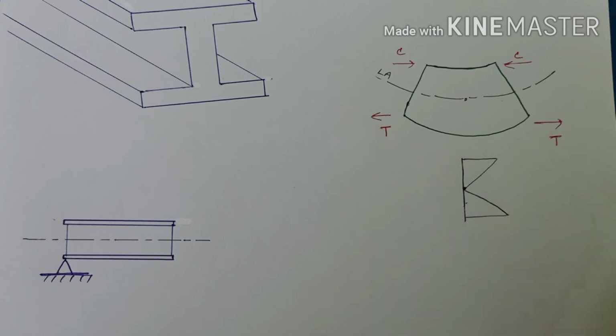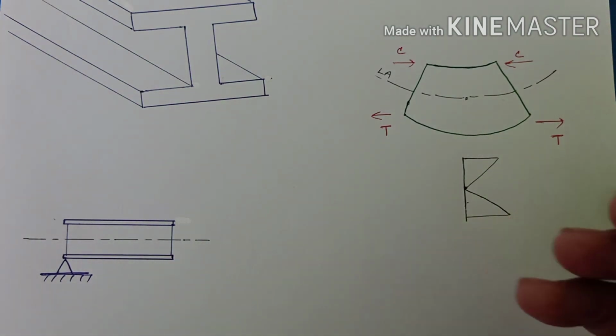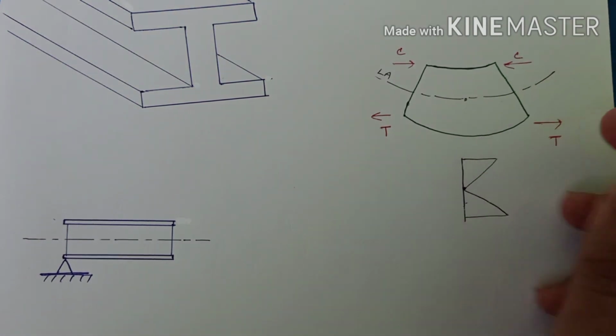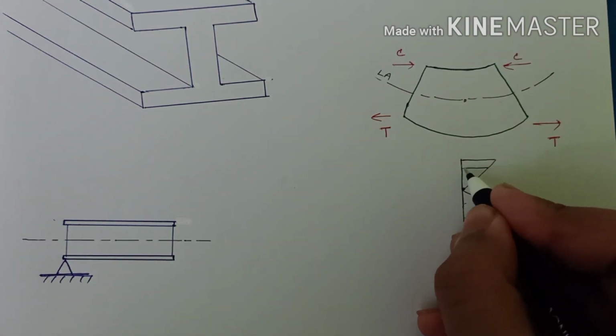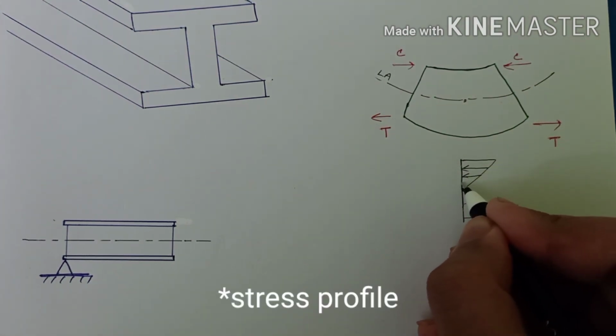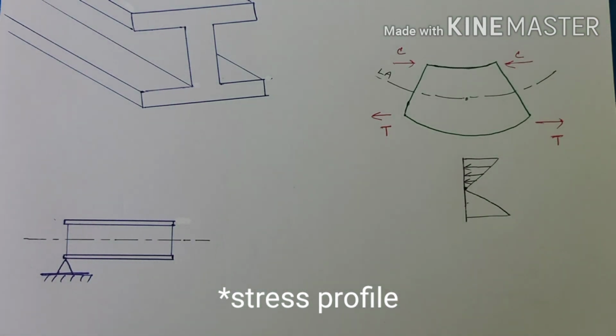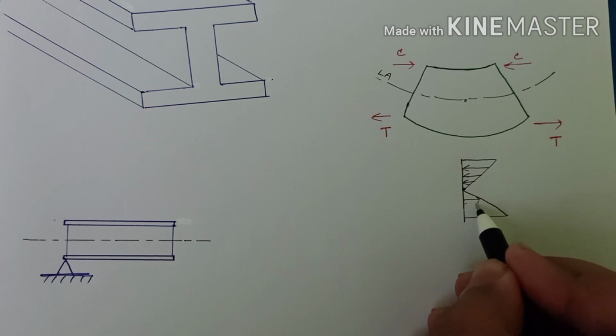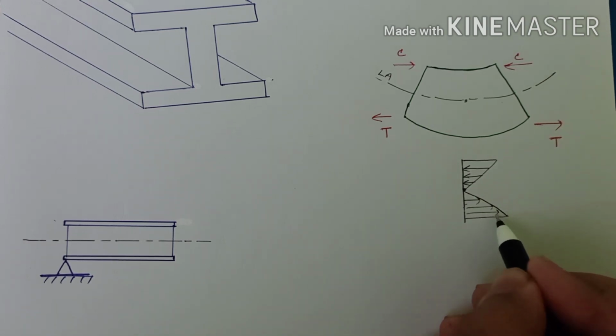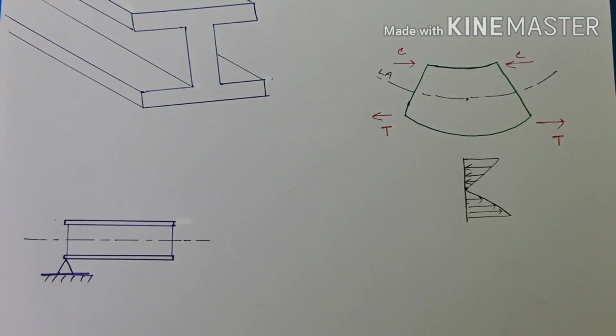Sorry, this is not symmetrical with this one, right? But see, the upper portion is under compression, so we can draw the stress profile like this, right? On the other hand, the lower portion is under tension, so we can draw the stress profile like this. So I hope this much is clear, right?